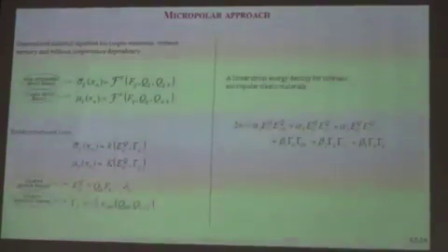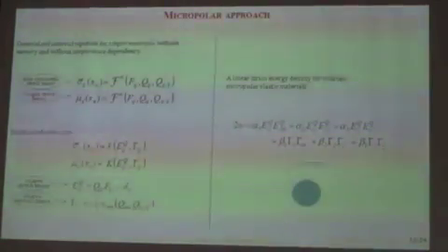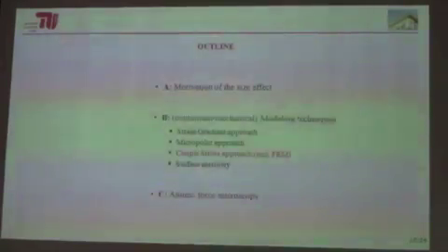Also here we can give a linear strain energy density for an isotropic micropolar elastic material, and here we also have to give all invariants of the strain measures with material parameters, and we can identify maybe 6 unknown parameters in this theory. So also a problem for doing experiments on it.